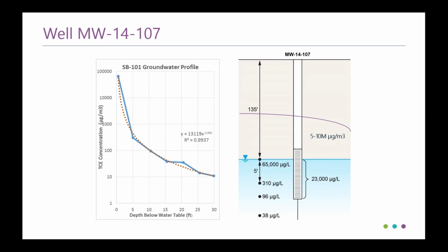And this is particularly significant when you look at the second number over there. We have a monitoring well in there, and they took a sample from that 10-foot monitoring well screen. That result is 23,000 micrograms per liter. If you just had that result, you might interpret this data differently. You might look at that and say, well, that's a condition that represents potential DNAPL existing or previously having gotten there. So you'd be looking at a whole different way of remediating this.